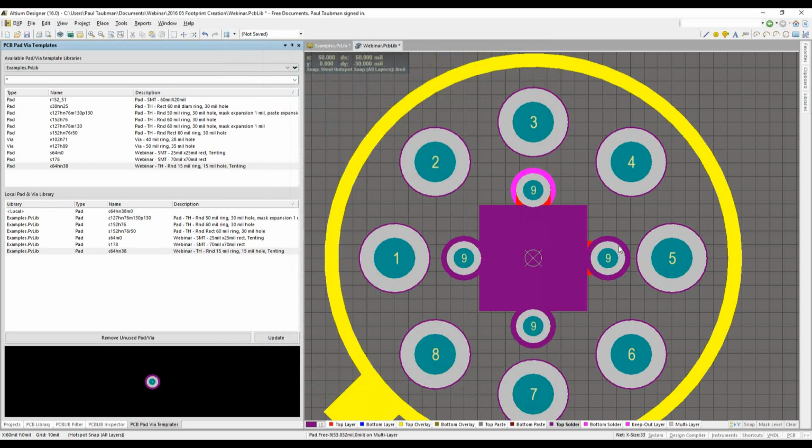So you'll see if I did this to all of these, the point here is that the only place opened in the solder mask is right here, and then you'd actually have the rest of this disconnected, even though the copper's over here. If I go to the top layer, the copper is over here. These things are actually under a solder mask, and as a result, it can't creep over into the hole.